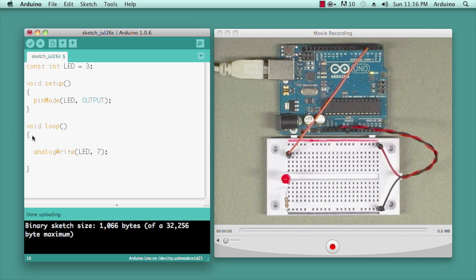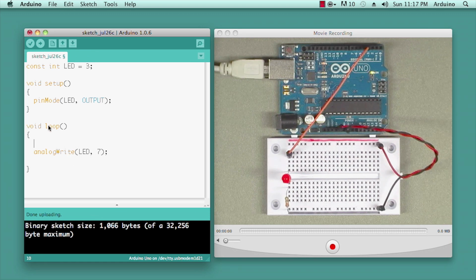So far, all of our functions have been executed top to bottom one time. Pin mode got run once, analog write gets run once, and of course, because we're in a loop, which in itself is a hidden control structure, we go back around to the top and we do it again. But we as programmers are not choosing to do any different number of executions of analog write, aside from the fact that we've put it inside the loop so it happens over and over again forever.